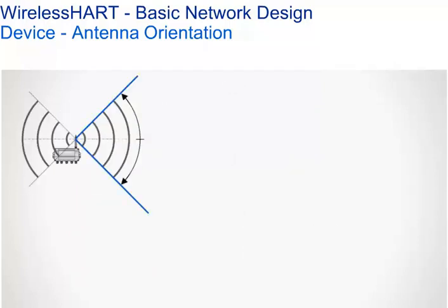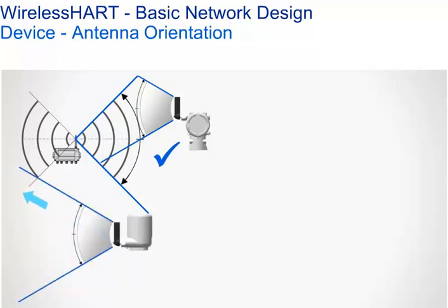Knowledge of signal transmission ranges is important because it can help when placing devices at different heights. Here we can see an example installation where the devices are not all placed at the same level. If we consider the theoretical signal irradiation, the WirelessHART pressure transmitter can communicate with the gateway. The link between the temperature devices is likely to fail instead.